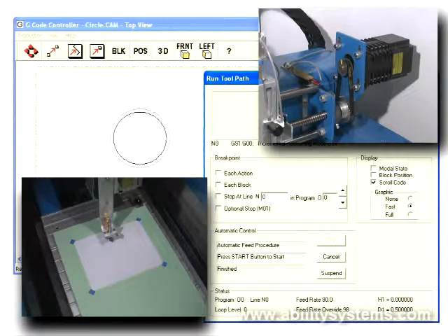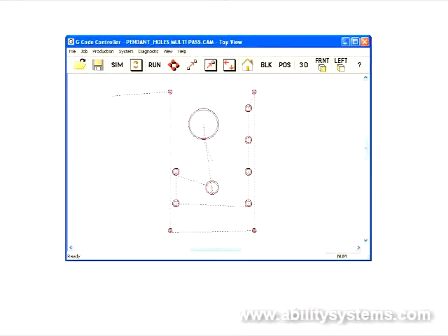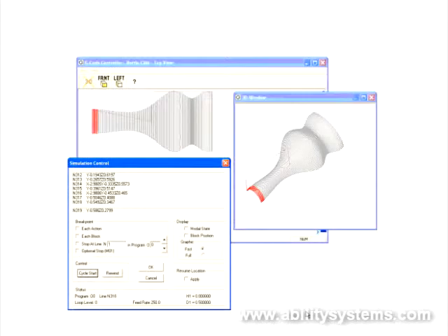Simple shapes like this circle are easy to script by hand in a text editor like Notepad. Even panels, like this, are relatively simple to hand code. More complex paths, like this, are more suitably scripted from CAD/CAM software that is designed for 3D modeling, such as BobCAD, SignLab, Mastercam, Visual Mill, etc. So in this case, the CAD/CAM software generates the scripts.